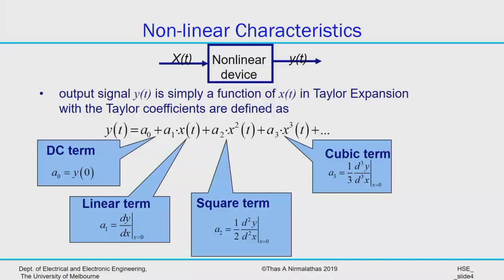Same way the third order term also. So it actually goes all the way to 5th, and in some circuits up to 7th we need to worry about, because that's the nature of that circuit, all right? And sometimes mostly everything will be 0, but 1 or 2 of them will be very dominant, and therefore we need to know. So there are largely odd terms, which are the linear term a1 x, and then a3 x cubed, and so on, or the even terms like the square a2 and a4 and so on. And they lead to slightly different mixing of frequencies. As a result, that's one of the things we need to be worrying about.